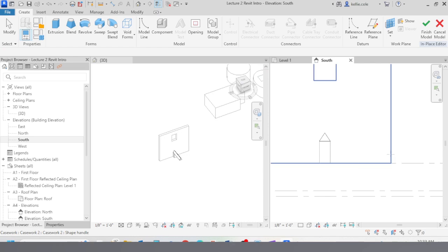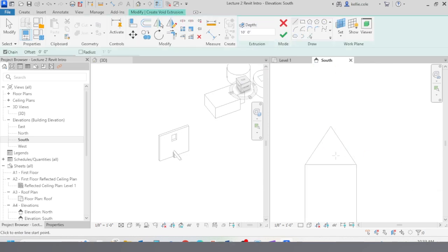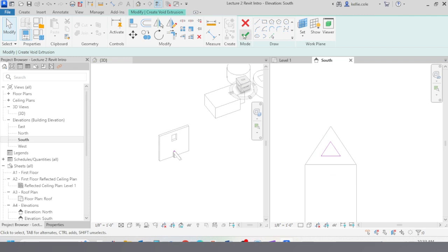And this time I'm going to use pick lines in order to offset a dimension. It's maybe 4 inches or 8 inches. It looks like 8 inches is too much. So in the left-hand side, change the offset to 4, tap existing lines to get a perfect offset, which still looks a little too big.